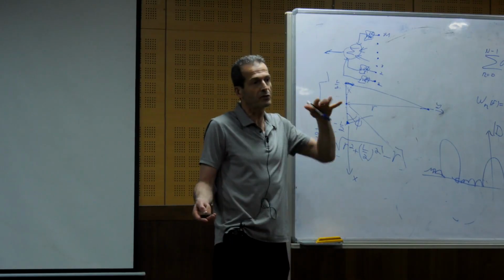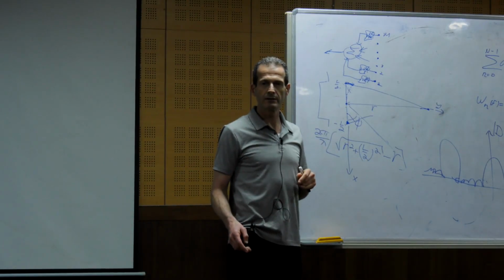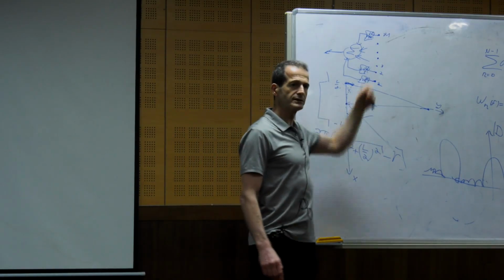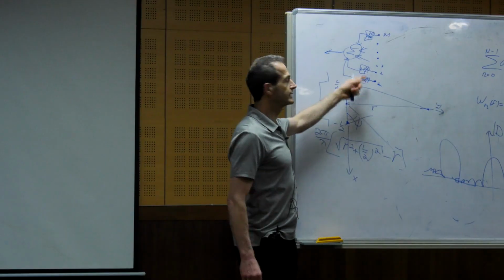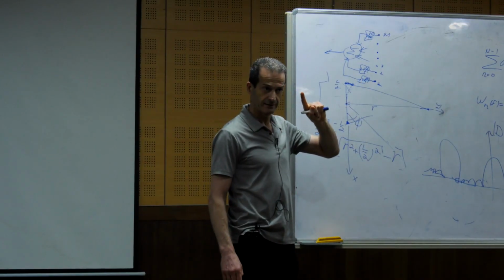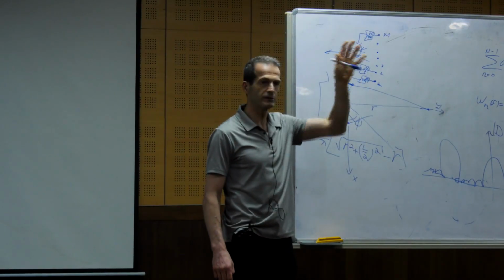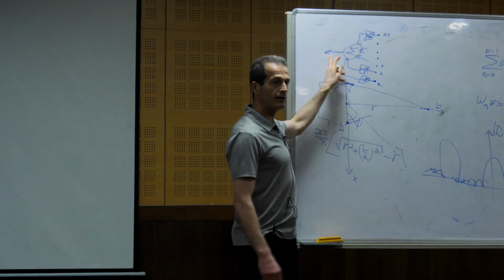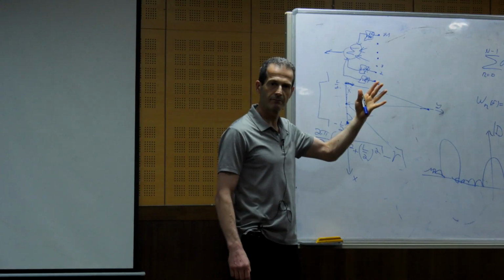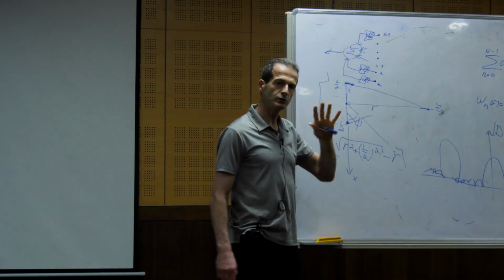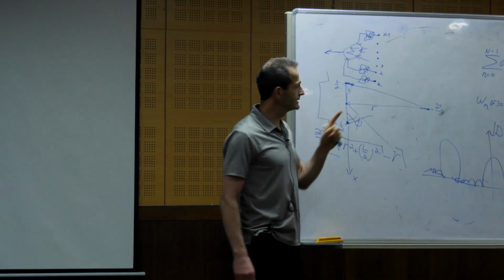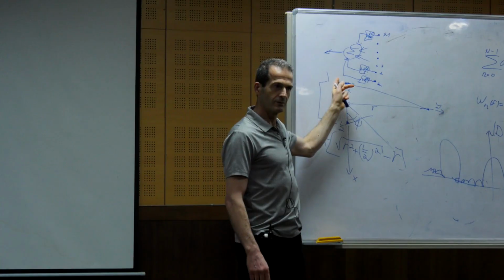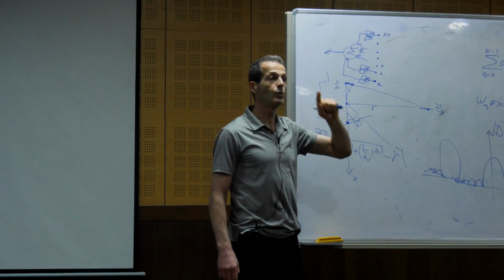Maybe it's okay, maybe the thermal noise is still low. But if the gain is very low, like minus 50 dB, it will be amplified at the output by 50 dB. So we need to be very careful not to design a directivity pattern with very low white noise gain.